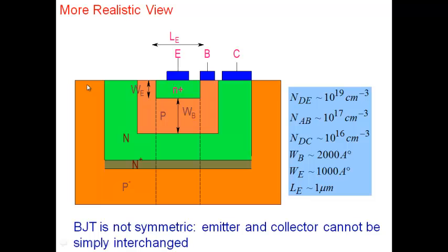And this is a planar transistor. Planar in the sense all the contacts are at the top. Note, emitter is here, base is here, and collector is here. Now, the way a bipolar transistor will be made is you take a piece of silicon which is only P minus. There's only boron and it is P minus everywhere. Then you create a region which is N plus. You'll see why it is N plus in a minute. You create a region N, then you create a region P and N plus, and you form contacts.